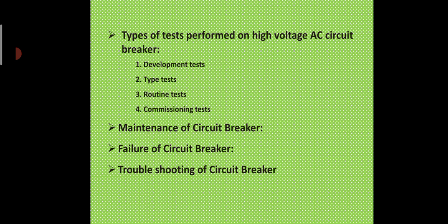Then SF6 circuit breaker. Properties of SF6 circuit breaker are toxicity, arc products, physical properties, dielectric strength, arc quenching, and electric breakdown. And handling of faulted SF6 gas. The toxicity is of faulted SF6 gas and solid arc products. In clothing and safety equipment: coveralls, hoods, gloves, boots, safety glasses, respirator, etc.